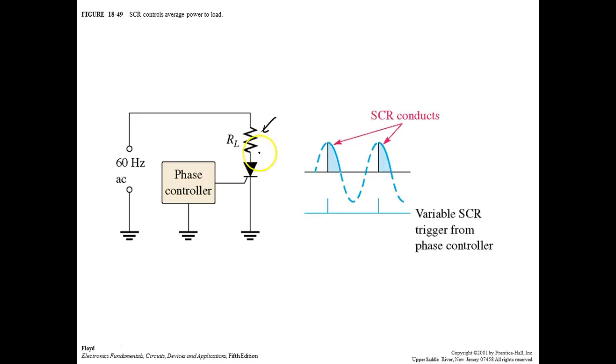When this goes positive and this goes negative, coming in like this, this is going to work as a half-wave rectifier. But we're going to be able to control where it conducts within that range. When we have our positive alternation, this is positive with respect to that, right? You understand that? So it has the ability to turn on. With this thing called a phase control, here's the gate right here. What they did is delay it and fire it right there.